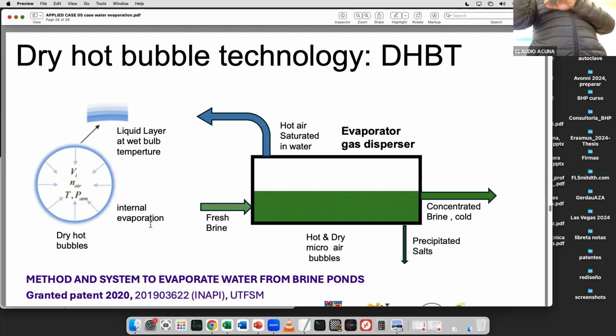If you don't have this droplet, you can have a demister to reduce that, something that collides the droplet, but you have some. Let's say in cooling towers, when we use evaporation to cool down the water, the drift, how many droplets of water are you losing? It's 0.02% of the total amount of water that you're circulating. So it's very little, but this very little, very high concentration, we put some ions in the solution, okay? But anyway, it will be very, very good quality water.